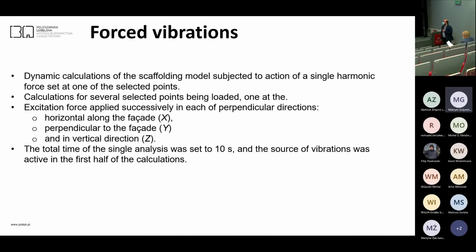So we have applied just a single harmonic force in one of the selected points in a single analysis, one time with one force, and we have observed the results: displacements in horizontal vibrations along the facade, perpendicular to the facade, and vertical vibrations. The analysis time was 10 seconds.